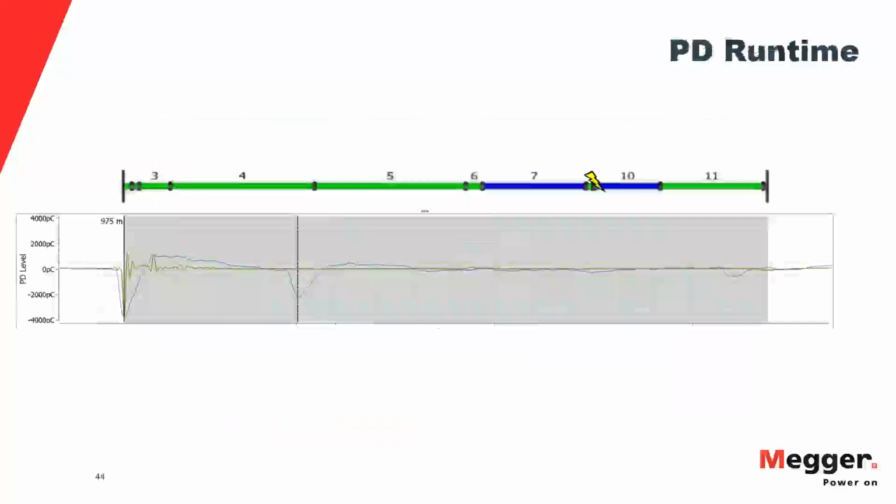Attenuation increases as the cable length increases, as that pulse loses energy to losses in the cable system. It basically lowers the magnitude of the signal. And what happens is a marginal signal can then become unmeasurable. The other phenomenon we have is called dispersion. Again, it's related to the length of the cable. As the cable length increases, the pulse gets wider and lower. Kind of similar to a TDR if you've used those. And that's because the cable filters out high frequencies. So we see here this nice, sharp, tall pulse, it has a lot of high frequency components in it. And as that pulse travels down the line, it loses more and more of those high frequencies. So we no longer have that nice sharp edge, and we wind up with this lower and wider pulse.